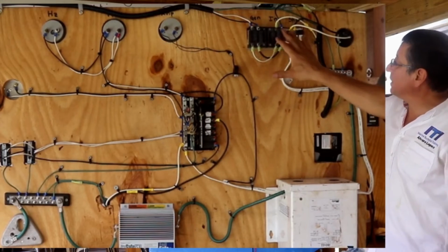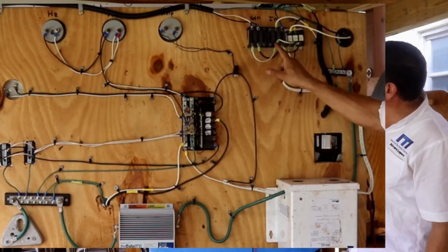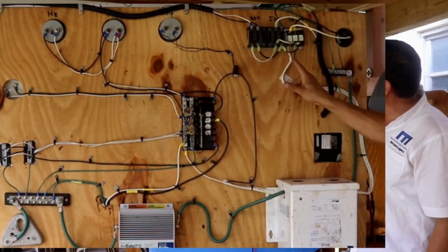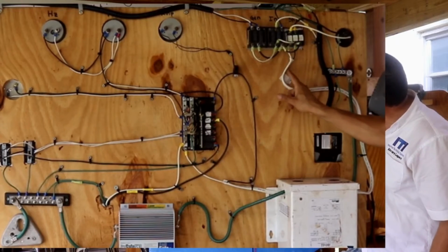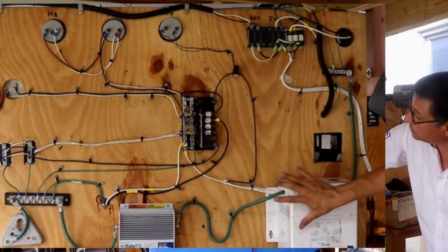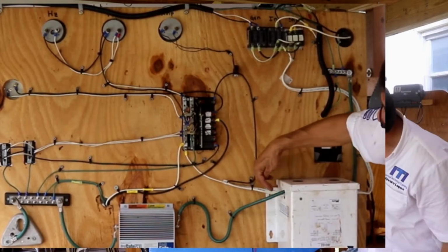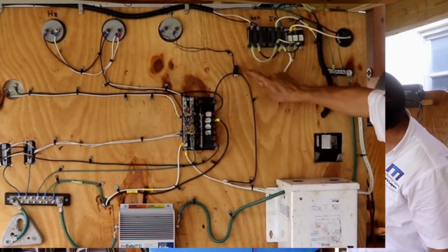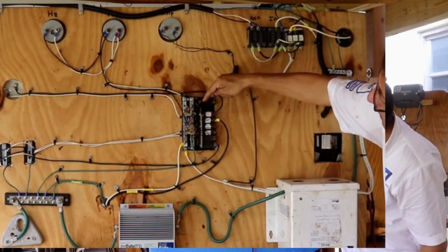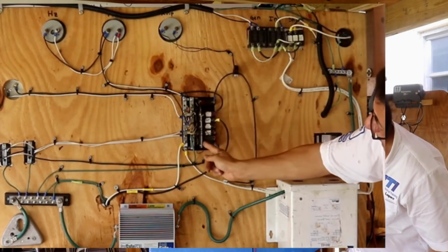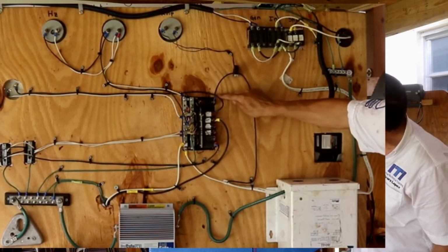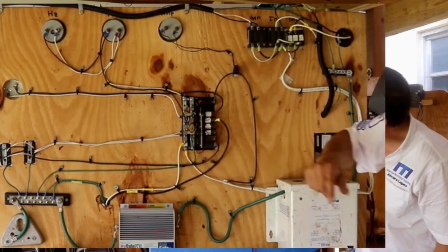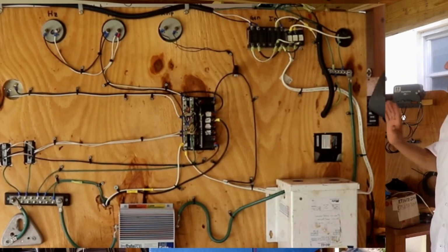And right now, I am going to connect the neutral of this with this, and the neutral of this with this. All of the neutrals are connected together, and from one of those connections, this is the neutral passing to the isolator transformer, continuing, and entering into the panel, the neutral bus bar and main breaker. After the main breaker, the hot line enters the hot bus bar, and this is the output of the breaker. This is the output for lights, this is the output for outlets, and this is the output for the battery charger.